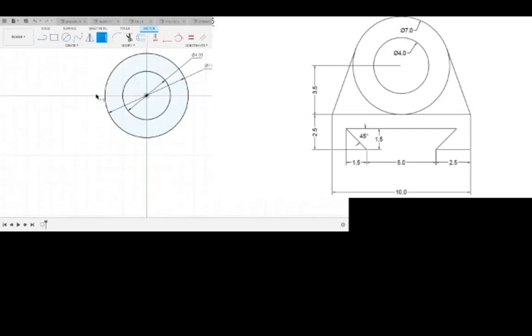Then we're going to want to make the dovetail section below it. So we could start off by taking a line here and defining that with respect to the center line along this little guy here. So now this is here, that's there. Make that one vertical and make this one a construction line. So now it's all a little bit more clean, a little bit less numbery than it needs to be.